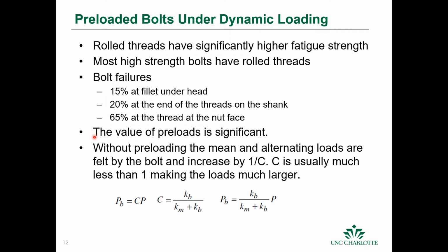So the point of these slides is that the value of the preloads is significant, and you may think, oh, I don't really want to load the bolt up in this application, and we're not talking necessarily about threaded holes. We're talking about bolts, which is a different design application. We're talking about bolted joints. Okay, so in this case, the preload is very significant to keep those materials clamped together and to allow that material to take up most of the load.